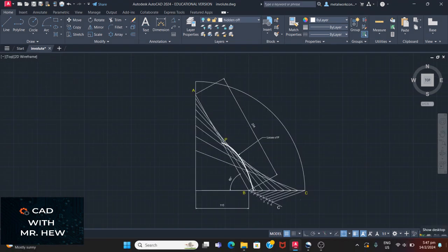Okay? All right, so there we have the measurements for how far B is from the wall, 113 millimeters. The angle is 65 degrees. It's leaning at an angle of 65 degrees to the horizontal, which will be the floor. And the length of the ladder is 232 millimeters. So what you do, you draw an arc from the intersection of the floor and the wall equal to the length of the ladder to get the last point, okay?